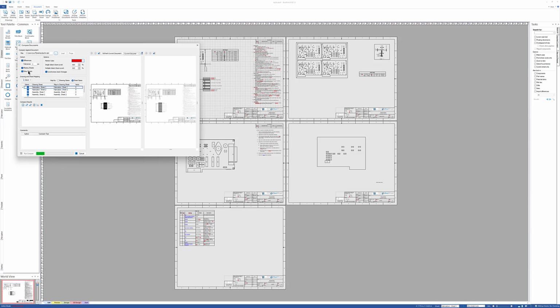You can have it look for missing and extra sheets. It's going to try to map the drawings by either drawing name or sheet name as you bring those in. You can always manually map them. What color do you want your errors to look, and what zoom level for one error versus multiple layers? Once we do get it done, we'll see the results of the comparison here, and then we'll have some options like being able to validate or add comments to the differences that we see.